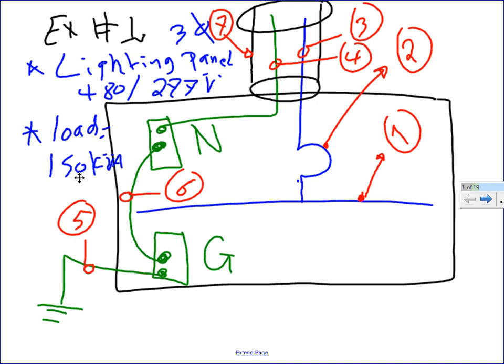Okay, so the first thing we need to find, guys, is a few things. Number 1, I want you to size, this one is referred to the bus inside the panel size. Number 2 refers to the overcurrent protection device that can reside inside the panel or ahead of the panel. Everybody can see that? Number 2 refers to the overcurrent protection device. Number 3 refers to the 3-phase conductors that are coming to this 3-phase panel. Number 4 refers to the neutral conductor that comes with this panel. Can you guys see that? Number 4 refers to the neutral conductor.